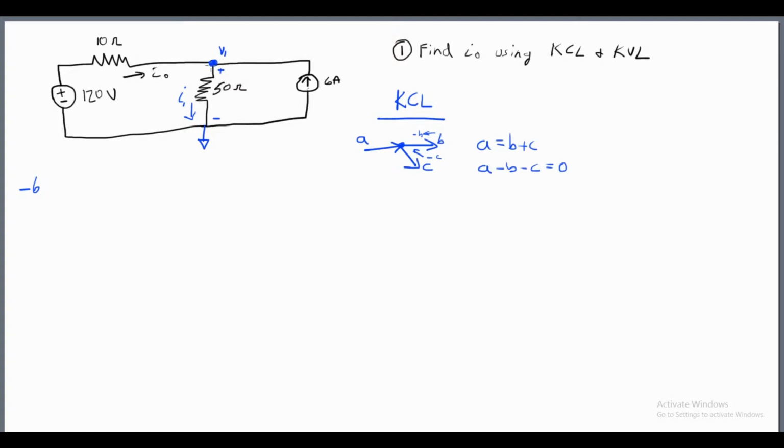That's going to be the next part of the circuit we're going to add. So we can do, let's see, V1 over 50, because we know through Ohm's law V is equal to IR, or the current is equal to the voltage over the resistance, and that's what we just did. We took V1 over the 50 ohm resistor.